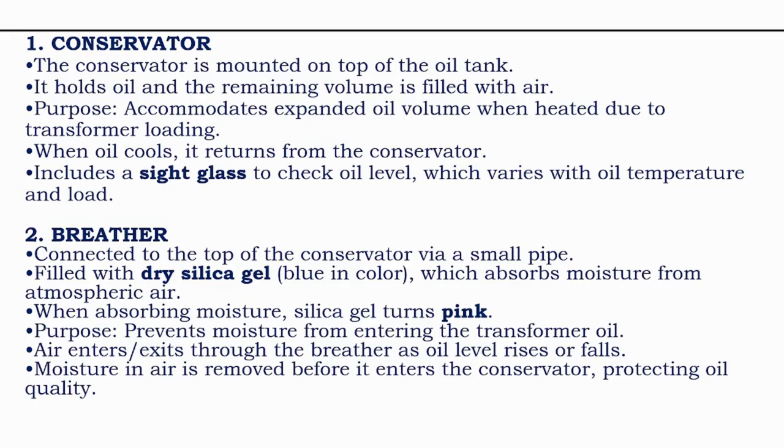And second one is the breather. Why is the breather required? The breather is connected to the conservator tank with a small pipe, and it is filled with silica gel. Normally silica gel will be bluish in color. When it absorbs moisture, it converts into pink color.